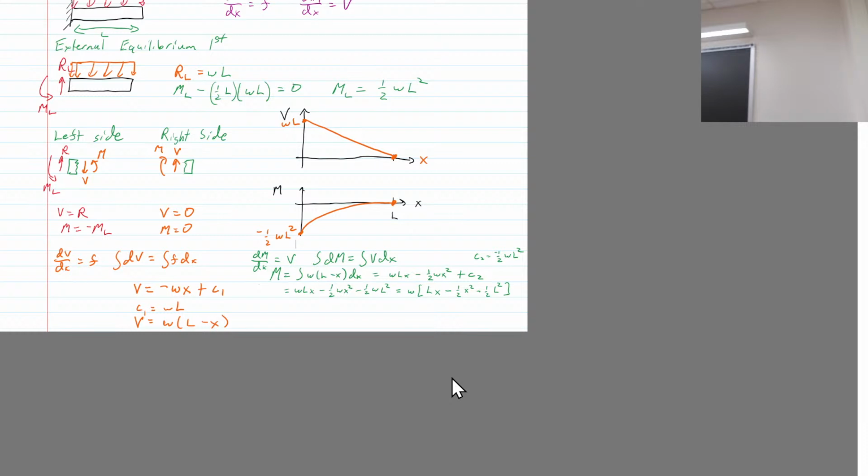If I have a shear force and we take a cross section, how do I calculate the transverse shear stress? There's no area for it to work on. It's sitting on the top of the circle essentially. So there's no transverse shear stress because of PZ at that particular location.